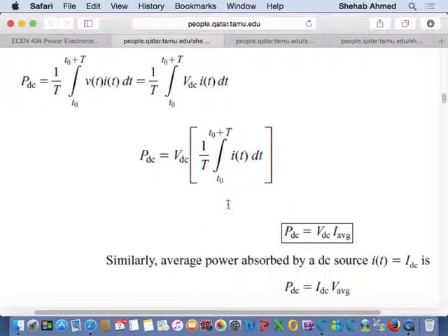And it can be the opposite. There are circuits where we have a very nice smooth DC current, but the voltage is a switch type of voltage. There are certain families of converters called current source converters, where instead of chopping up voltage to create a different value of voltage, you have a fixed DC current coming in, and you chop up the voltage to create another value of current. So you're controlling current instead of controlling voltage. We will discuss that briefly later as well.